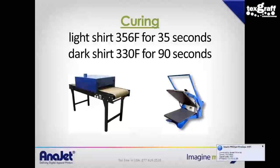And because of that, that's the piece that washes out. So she took a little laser gauge with a temperature reading on it, and sure enough, I was right on. There was a section of her heat press that was basically cold. The rest of the heat press worked fine, but that section was cold, and it wasn't curing the ink fully in that area, and because of that, it was washing out.